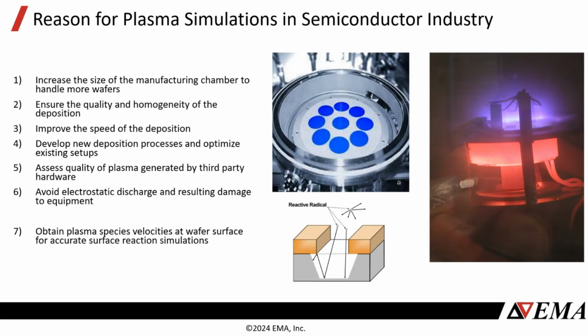And at that surface, there's a lot that can happen depending on what you're trying to do. You can carve out material, you can sputter material, you can deposit material, right? But at the end of the day, what you need to do is model the plasma in 3D inside the chamber to be able to properly understand how those ions are going to interact with the surface. To properly model the 3D simulation, the 3D distribution of the plasma, you need to leverage the technology that we'll be discussing today for electromagnetics and things like that.